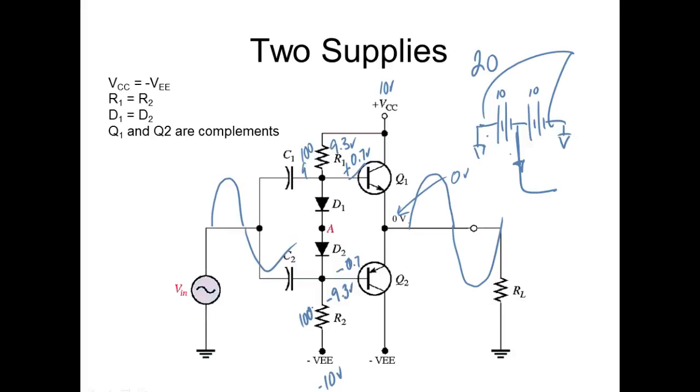We start off from what? 0. We go up. We drop back down to 0. We switch negative. We come back to 0. What is that? That's AC. So these are stereo amplifiers right here. You cannot put DC. We do away with the capacitor. We don't have to put the coupling capacitor in there. So the output of your amplifier is AC.